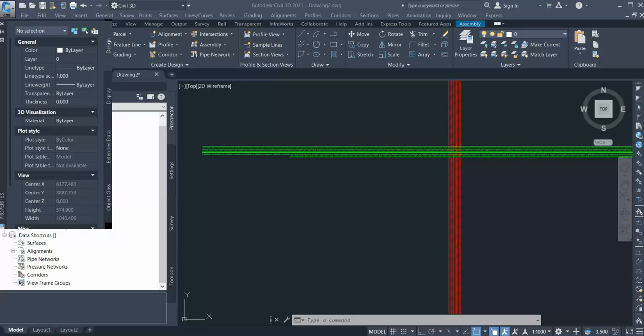Next, if both roads are in an urban scenario, if you have two arterial roads, major roads where your speed is 80 or 100 kmph, then you also go for the interchange option. So you need to keep in mind where you need to suggest or provide interchanges.